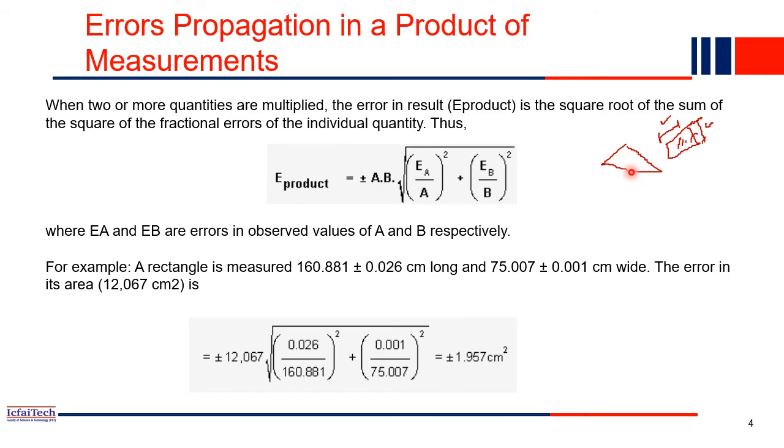That means EA is the error in the A measurement. You have two measurements here; this is a total rectangular area. This length you find: A is the significant number plus the error part EA, which may be very small. Similarly, for the other measurement, B is the significant number plus the error part EB. Now how will the error be propagated from the distances to the area?